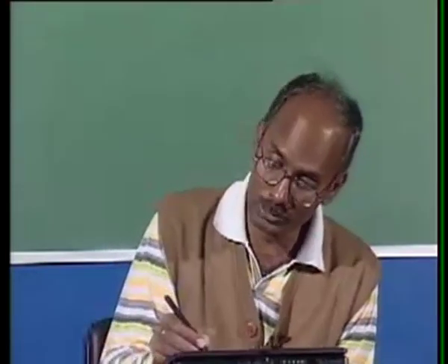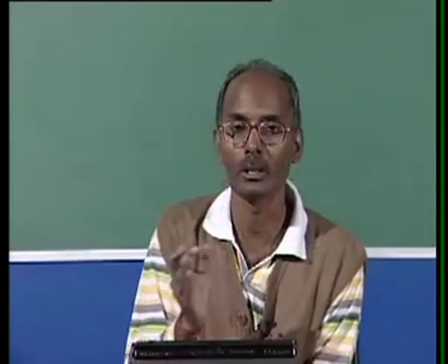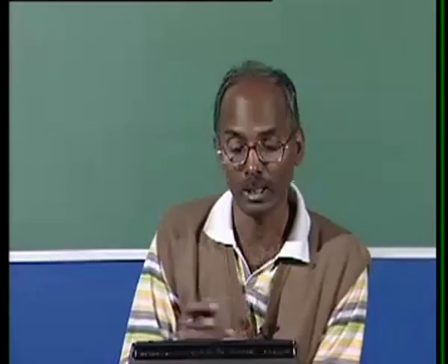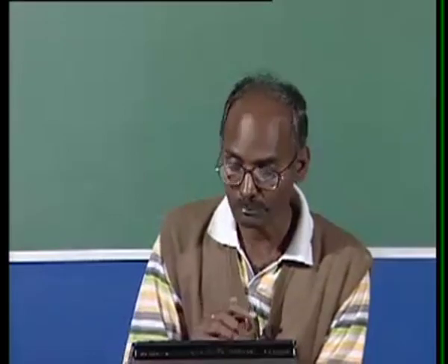So this consumes reactive power every time if you are using the induction machine. Here I am talking about the induction motor. If you are using a synchronous motor, no doubt you can operate in both leading and lagging conditions, meaning you can generate reactive power. But the induction motor cannot do that. Every time it consumes reactive power.